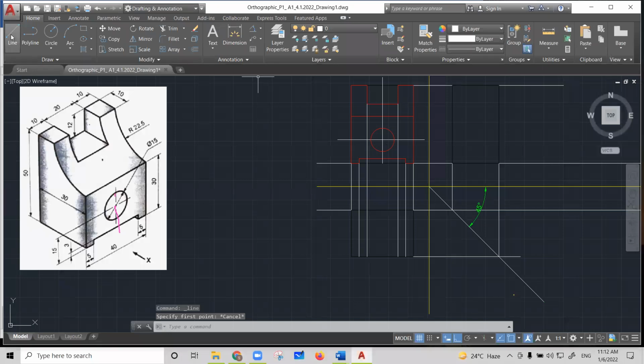Okay, so first of all we have to get the top surface visible to you. Suppose if I go for annotation, see, if I say surface number 1, 2, 3 and this 4. Okay, see in top view 1, 2, 3, 4 is visible, right? So accordingly you start taking these edges, marking the edges one by one. So first of all, I will get surface 1. How will I get it? By taking the projection. I already got this, then I will take 10 millimeter down. Then I will be closing.